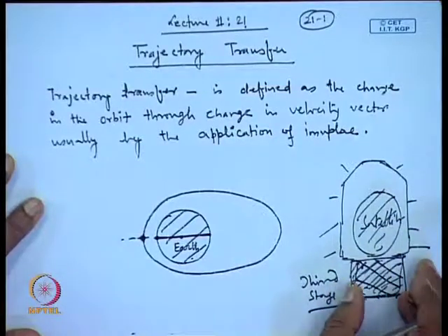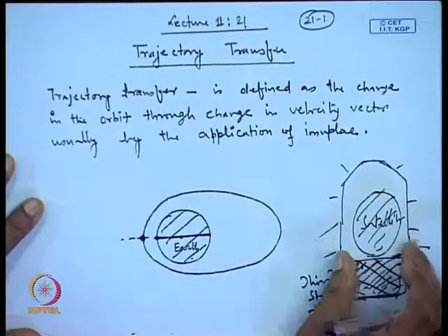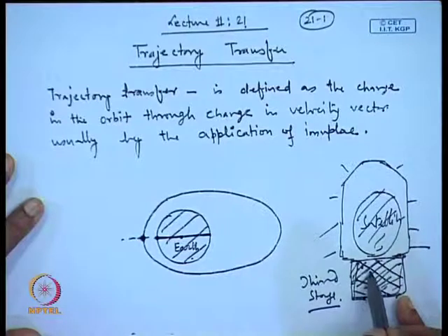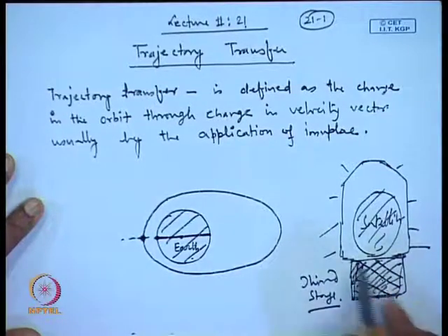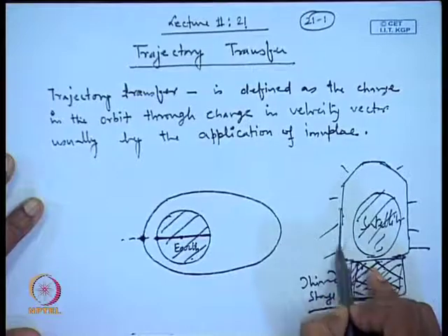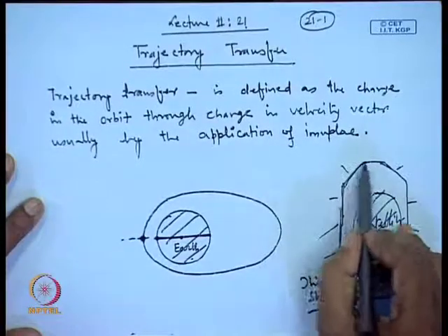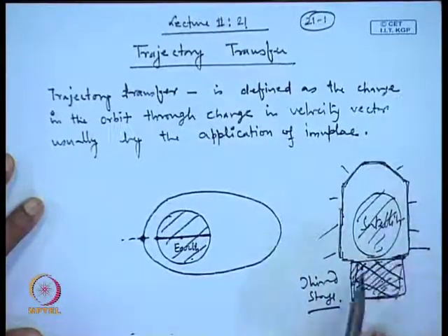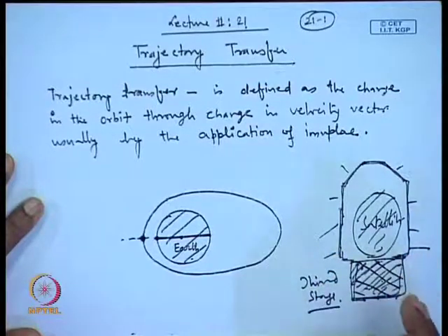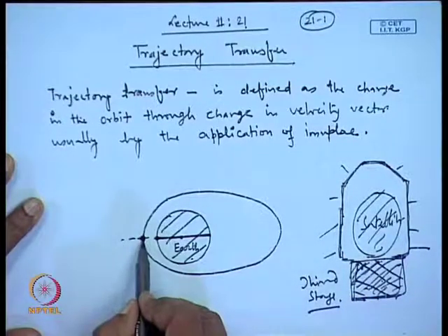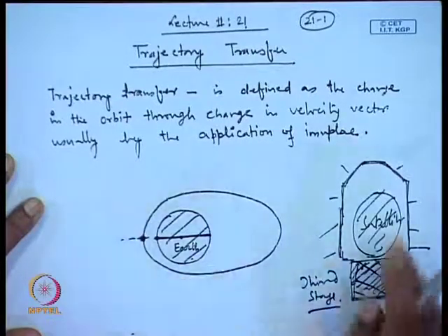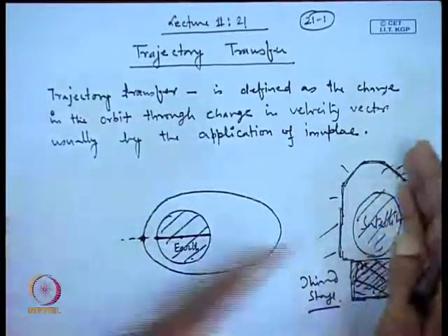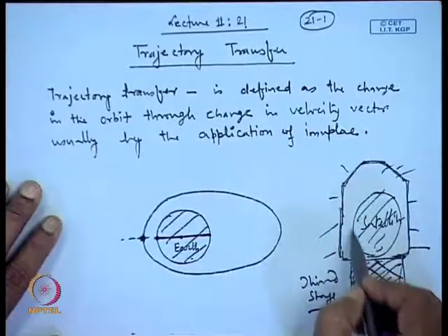Now, if you want to take it to a further height along with this rocket, you have to spend fuel for this extra structure which is coming because of the presence of the rocket. So, you are going to lose energy. Therefore, the propellant mass required will be much more. If you inject the satellite at a smaller altitude with high velocity, your rocket is gone, this part is taken off, and only the satellite is remaining.